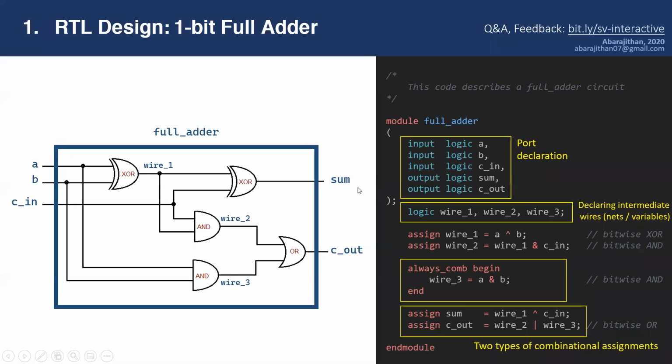The output wires, sum and C out, we connect to the wires we create over there. Look at this carefully: if you give the wires you create outside the same names as the input ports A, B, C in, then you can connect them very easily using a shorthand.